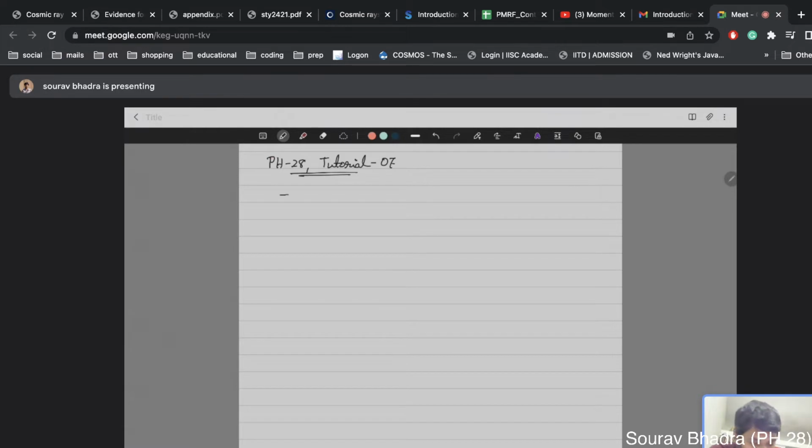As you know, our moment of inertia tensor is denoted by I_jk, where it is a tensor. Now, how does this look? It looks like the sum over i of m_i (r_i squared delta_jk minus x_j,i x_k,i).